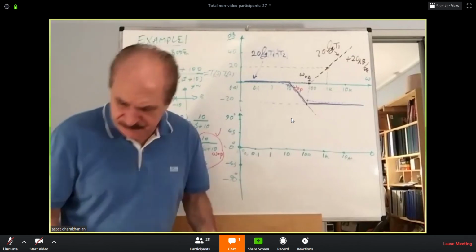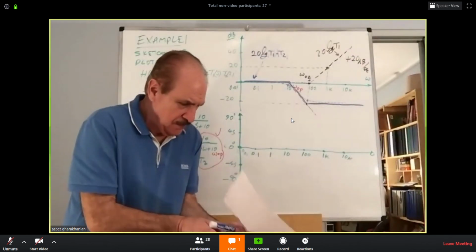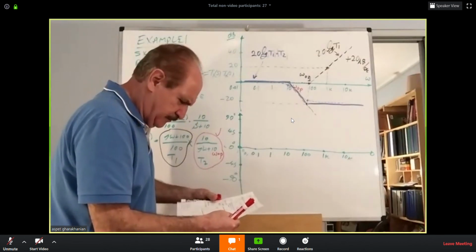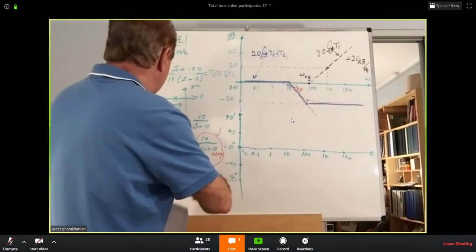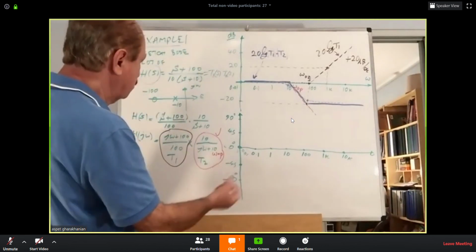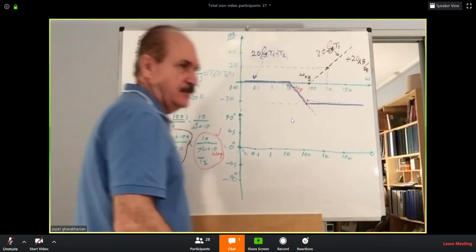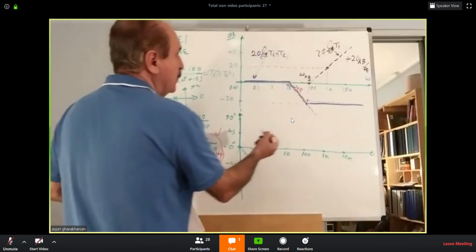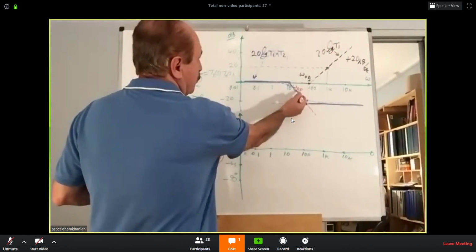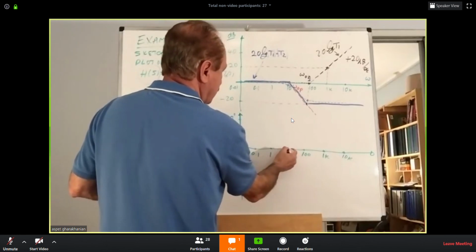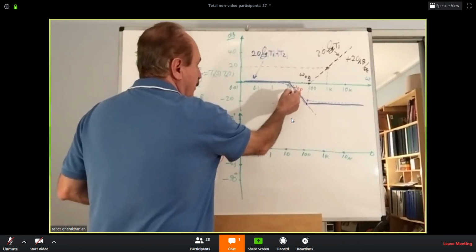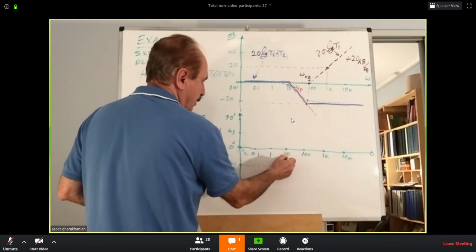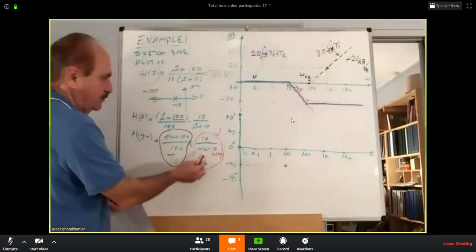Okay, here's how to do that. For the transfer function, the pole, let's start with T2, the pole. For the pole, you need to find your breakpoint, omega O pole, which is at 10. Here, exactly here. We know that pole is creating 45 degrees lag. So you will mark that point here.